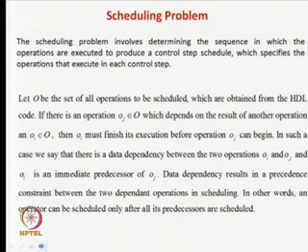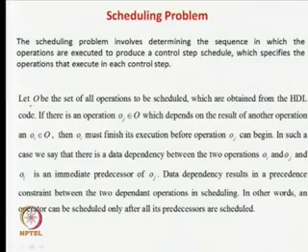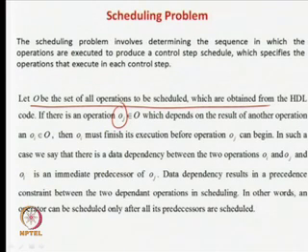Okay. So, now what is the scheduling problem? I already said that in a CDFG we have some operations. This procedure will try to allocate a time step to each of the operations. Let O be the set of operations which are to be scheduled. You can easily get the set of operations from the CDFG, and each individual operation Oi belongs to O. Each of them has to be given a time step. You can say that this happens in time step 1, this should happen in time step 2, and so forth.